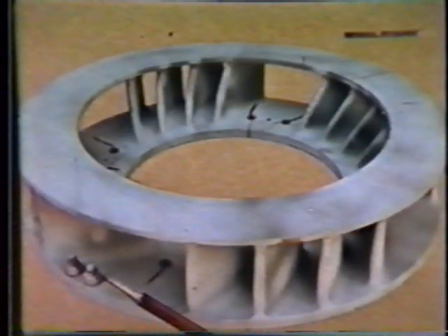This magnesium casting shows a number of visible dye indications. The red spots and splotches indicate surface porosity and possible micro-shrinkage. Several large cracks are visible at bolt holes. We know they are large by the amount the penetrant has spread. Another view of the casting. Indications at bolts are typical of non-relevant indications resulting from assembled parts. This particular example shows the outline of an inclusion. Non-relevant indications appear in threads and at lockwire hole.